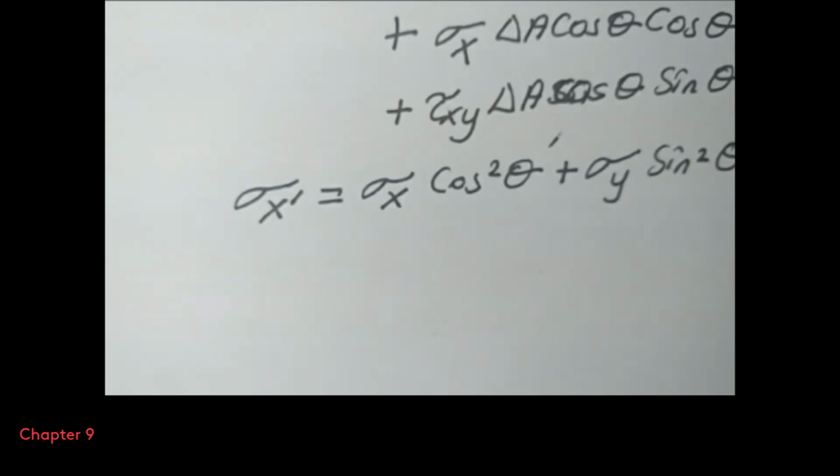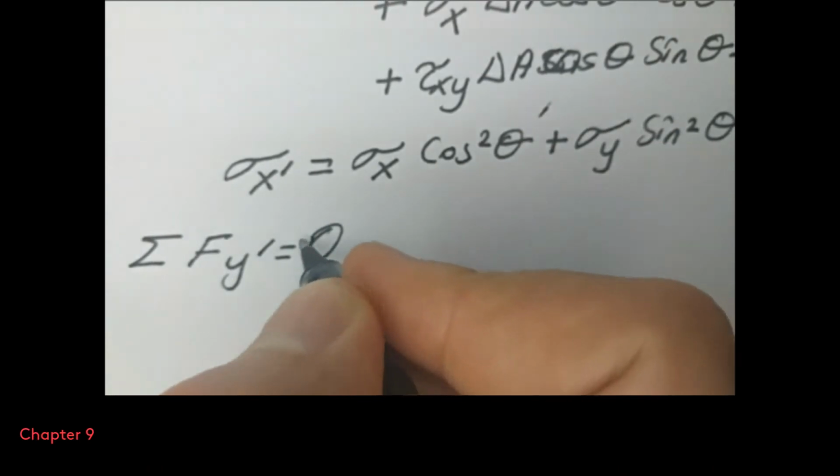In fact, we can write the same equation for the y prime direction. If you write the sum of the forces and say that the system has to be in static equilibrium, you can write the forces in that direction.